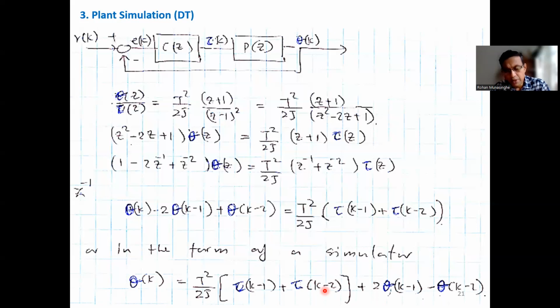Okay, so this is basically open loop simulation. You give a torque and the system will respond to that by turning the satellite. When you change the torque, it changes. When you reverse the torque, it starts decelerating if it is already moving in one direction, and then slows down and then turns the other way around. So that is the simulation. But what we really want here is not the simulation, but we want to control. Okay, we want to control.